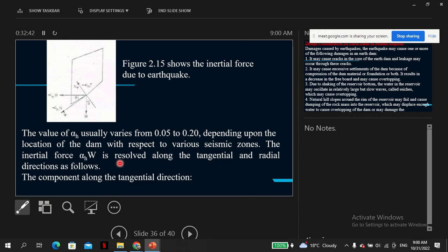But you have to check, as a diligent engineer. In some cases earthquake might be higher, but normally the practice is you choose the maximum of earthquake or wind, because the probability that maximum wind and maximum earthquake occur at the same time is nearly zero. So you choose the maximum of earthquake or wind, with the live load and dead load combination, and you design for that worst scenario.